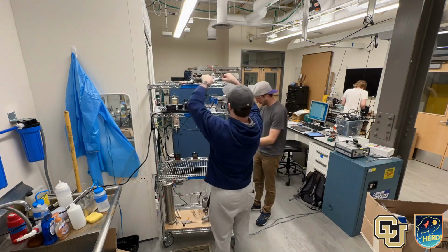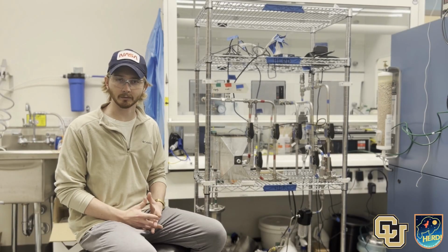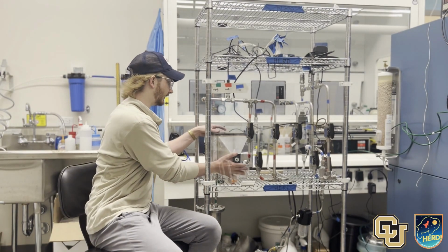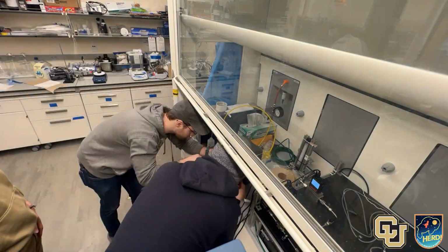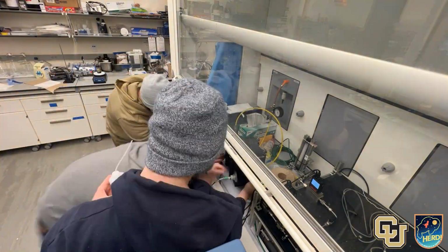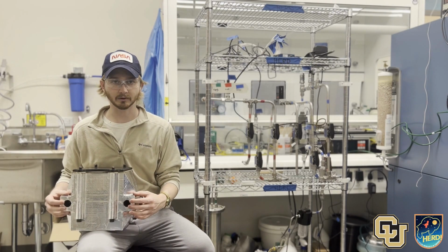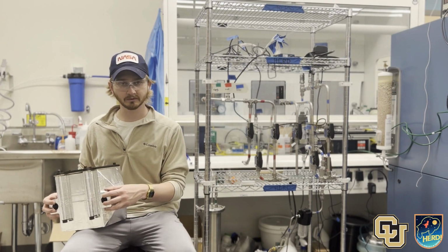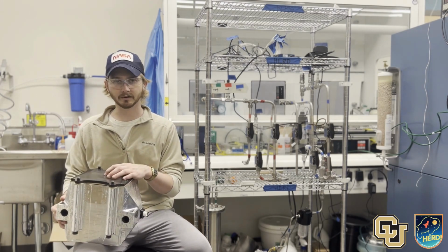My name is Chad Flieger. I'm the project manager and the engineer responsible for the carbon dioxide removal solution. In this case, this is the lithium hydroxide that would be enclosed in this 3D printed box. Essentially the air will flow through with CO2 into this cavity, and through these holes there will be ports for CO2 probes mounted on the inside, as well as thermocouples coming through the top here to measure temperature.